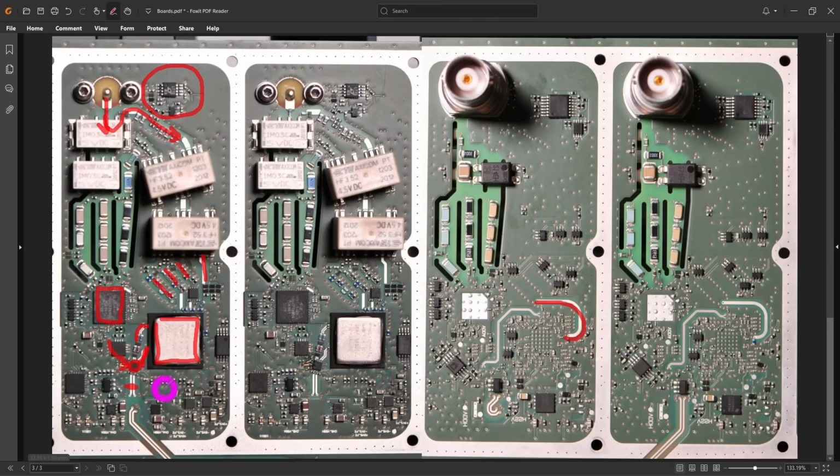And I'll explain to you minor differences between some of these channels at the same time. There is a very high precision 20-bit DAC over here, and that could be used for doing the DC calibration loopback of this, and perhaps some of that may be responsible for applying the DC offset, although I think that is almost certainly done inside of these chips in order to be able to be close to the analog front end. But yeah, this is probably a calibration thing, and there's one in every channel as a result. So yeah, pretty complicated. On the other side of it, you can see some further capacitors and attenuation resistors passive in the front, and another big protection circuitry here as well.